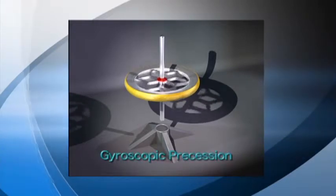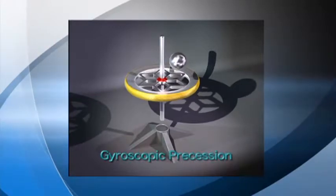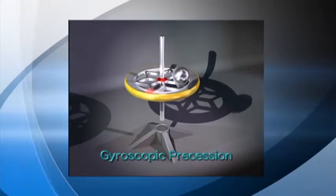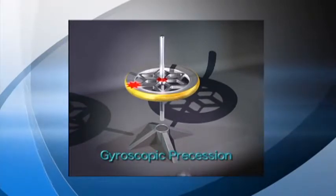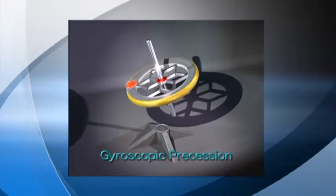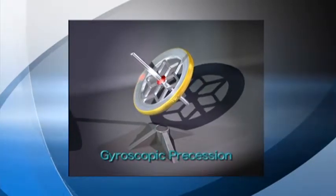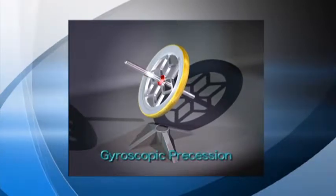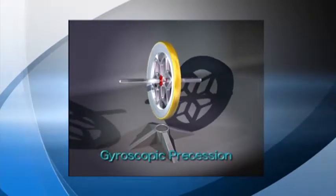Now, if we apply a force to the gyroscope right here, where this red dot is shown, we can see that the resultant force will actually not cause it to tip towards us, but will actually cause it to tip right here where this red dot is shown, or really sideways and in the same direction as we applied that force. We can see right here that gyroscopic precession has caused that gyro to tip sideways.